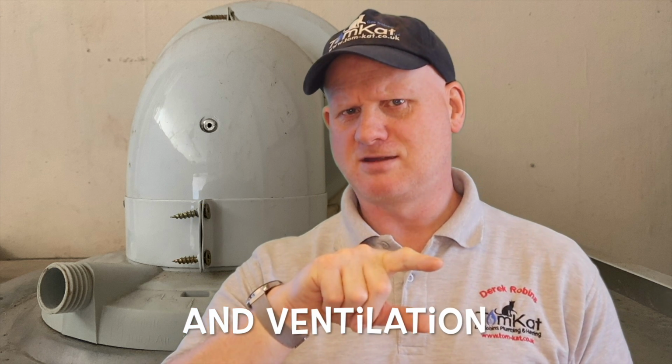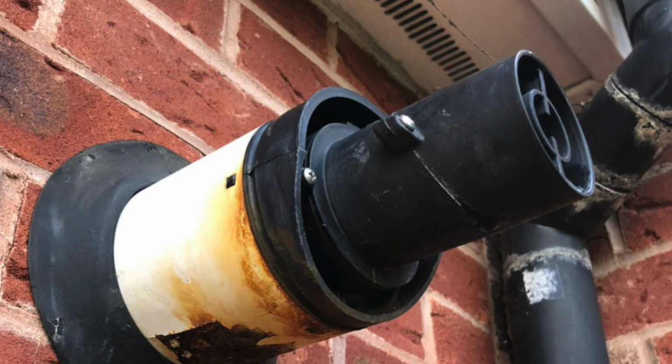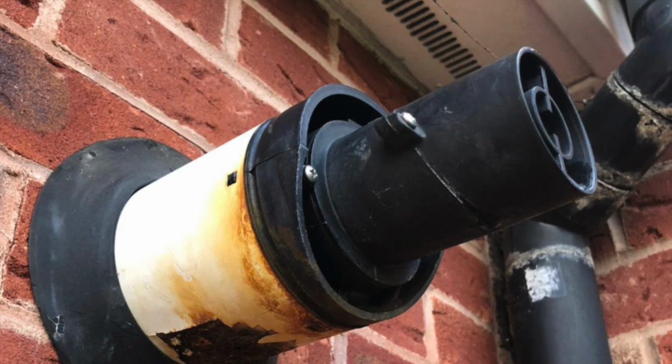But two at-risks don't make an ID. Only two not to current standards on fluing makes an at-risk. And if it's an open flued appliance, you get one fault on an open flued appliance on its flue system, then that automatically becomes at risk. So two not to current standards on room sealed is at risk. Just one fault on open flued is at risk. Now this picture represents you going to service this Worcester boiler.